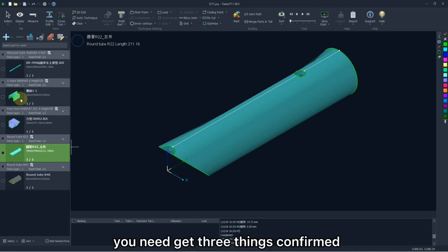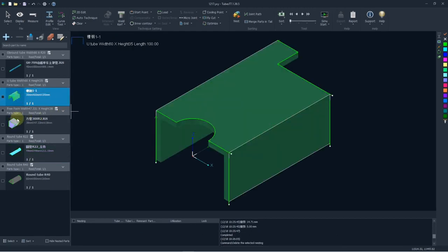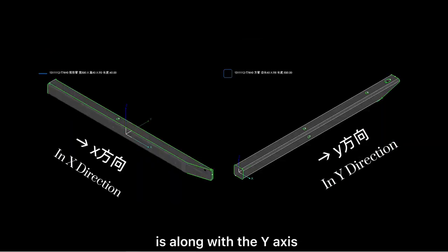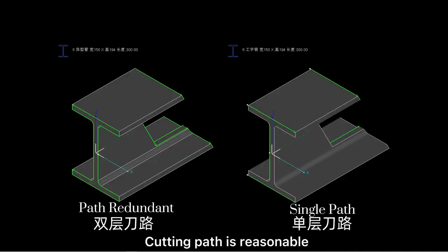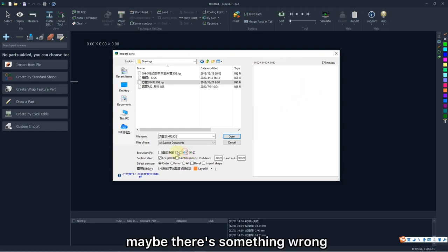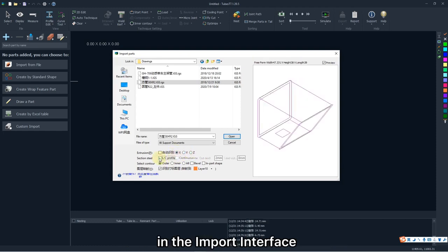You can browse the parts respectively to check if they are imported correctly. To ensure that, you need to get 3 things covered. The section is identified correctly. Extrusion direction is along the y-axis. Cutting path is reasonable. Generally, you need to check that there's no redundant cutting path. If the imported part cannot meet the requirements above, maybe there's something wrong in the import interface.